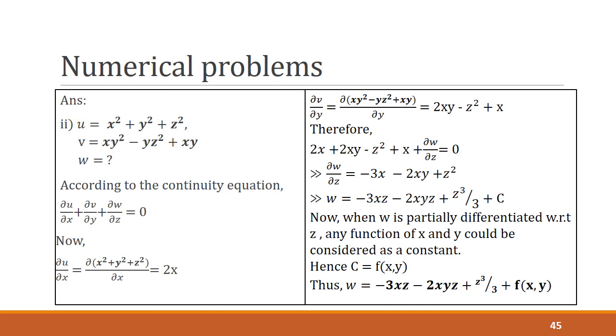Other problems, like checking whether the flow is steady and incompressible, can come, where you have to apply the continuity equation and check whether ∂u/∂x plus ∂v/∂y plus ∂w/∂z goes to 0.